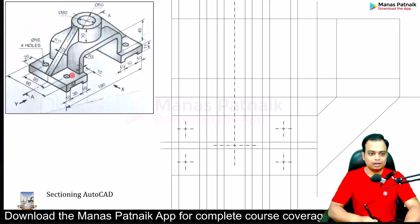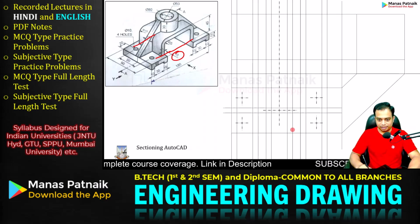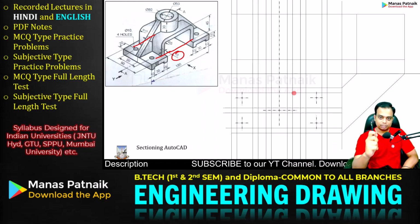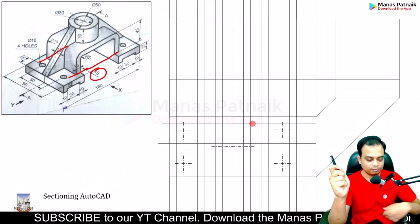What is the next step? In the next step, take a look at this. One more guideline. Here also. What is this distance? Sir, this distance is 10 millimeters. So from here, 10 millimeters, and from here, 10 millimeters. Done. So all the guidelines have been made. You just need to make sure that you've got an edge pencil. Okay. And now you start making the final top view.